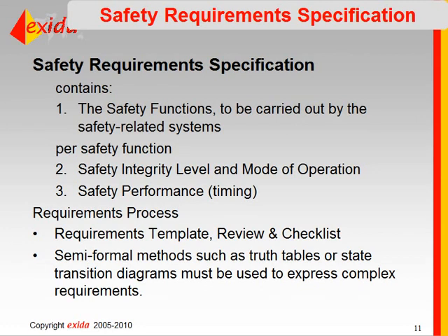If a hazard has a chance of occurring once every 100 years, and you install a safety system that 99% of the time will prevent that hazard from actually causing any harm, then you can reduce the risk of that, or the probability of a dangerous event, to be much less than once every 100 years, maybe once every 1,000 or 10,000 years.